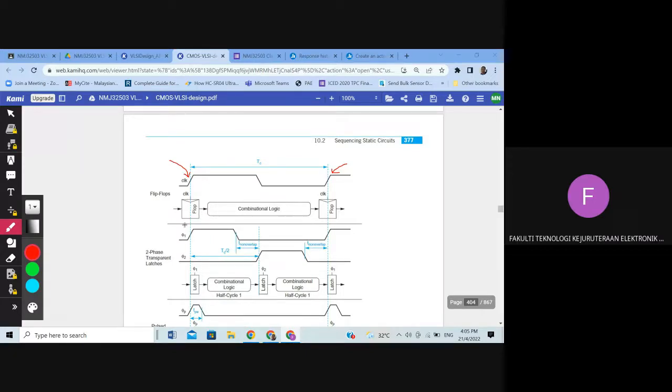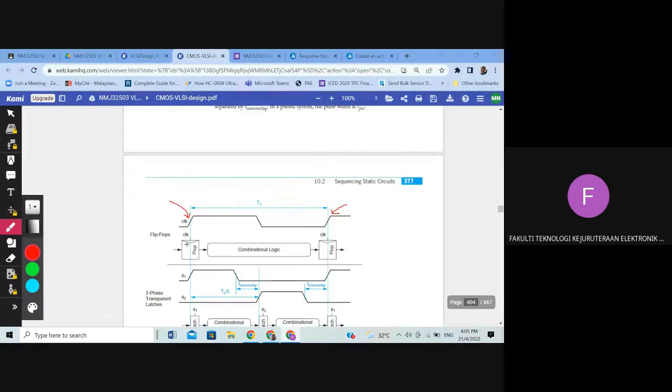So when the input goes to the flip-flop, that data will go through the sequencing process, and the data that arrives early will wait for the data that arrives late, similar to the concept of the sequencing element of combinational logic or static circuit. When it gets all the data ready during the rising edge of the clock, it will pass to the combinational logic.